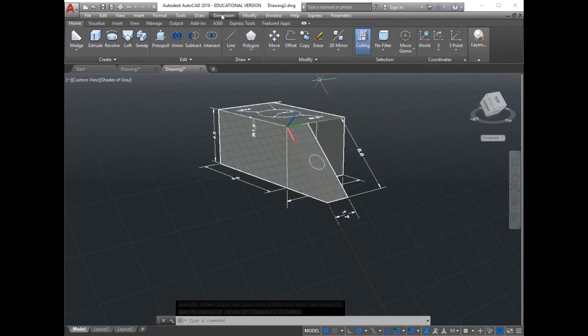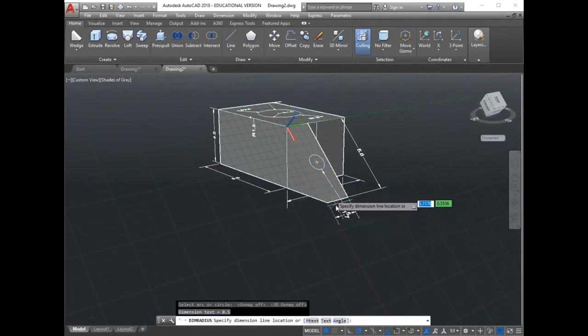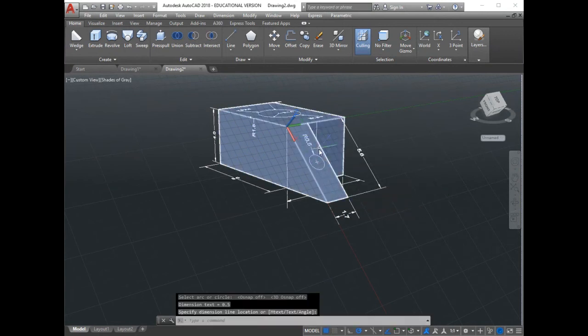Very simple. You can go for dimension, and then you go for radius or diameter, whatever you like, and then you simply pick up before you proceed, guys. Deactivate all the snaps just to be sure wherever you locate your mouse, it will be there. And then you go for selecting that one, selecting the circle. Here you go, guys. Wherever you put it, it's as if you are writing down these numbers on that surface. Clear, guys? And I think this is the most difficult part in your business.